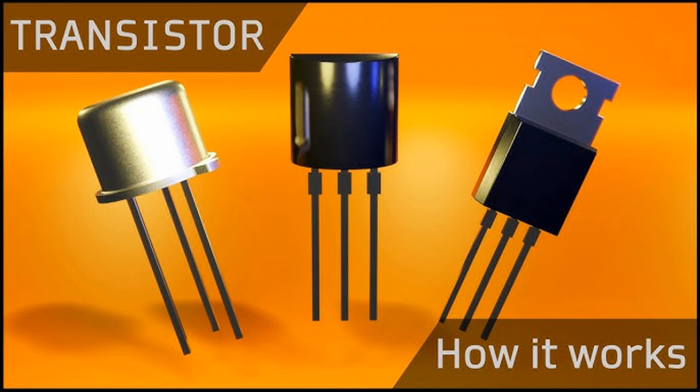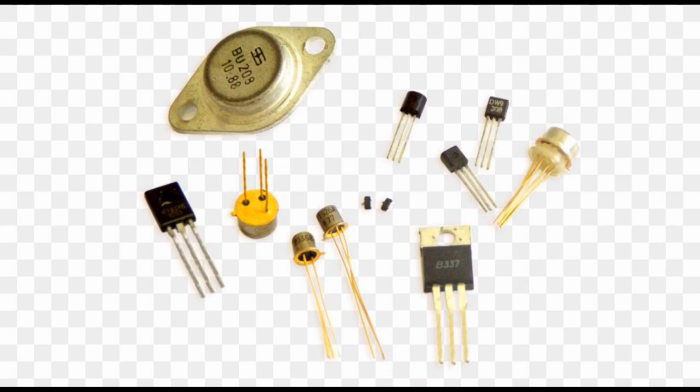Here's how P-type materials are created and their characteristics. Doping. P-type materials are typically created by adding specific types of dopant atoms to intrinsic, undoped, semiconductor material. Common dopant atoms used for P-type doping include elements from group 3 of the periodic table, such as boron B, aluminum Al, or gallium Ga. These elements have fewer electrons in their outermost energy level than the intrinsic semiconductor material, usually silicon or germanium. When they are introduced into the crystal lattice of the semiconductor material, they create holes in the electron structure.